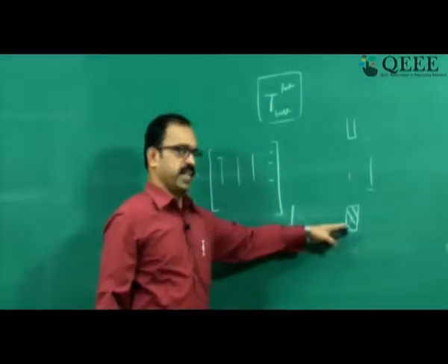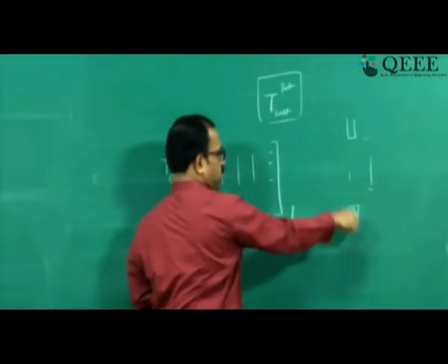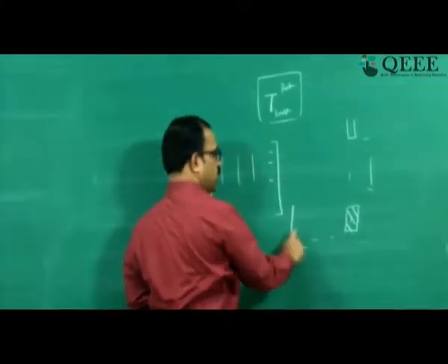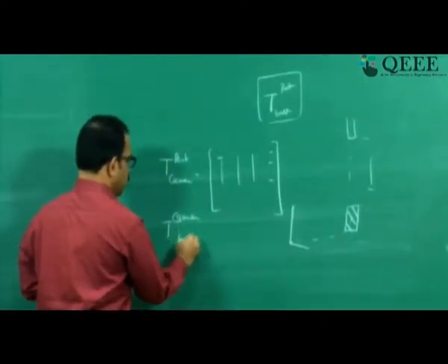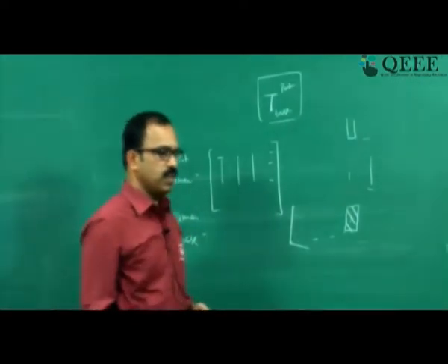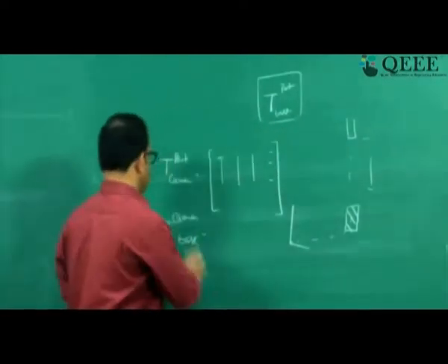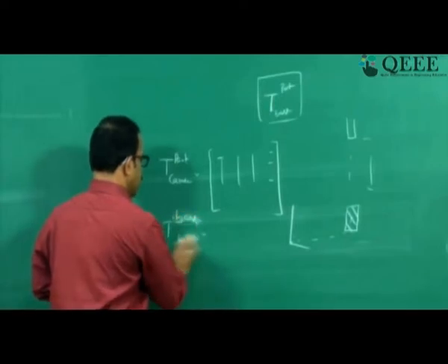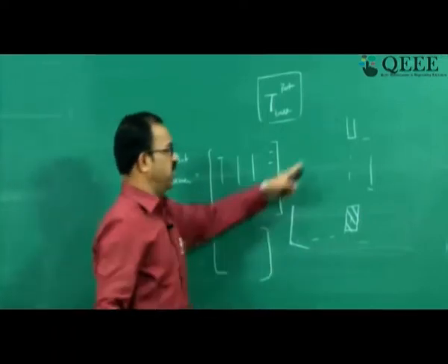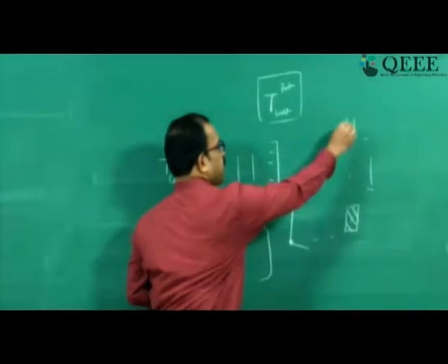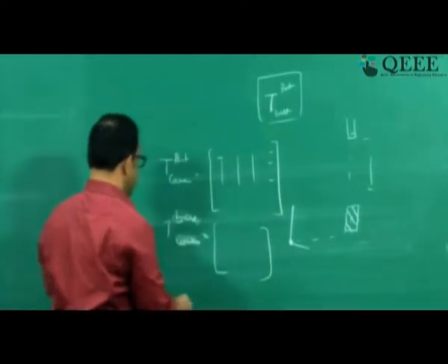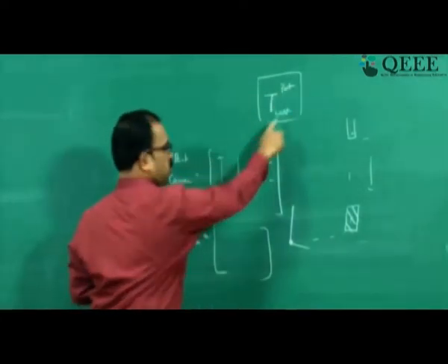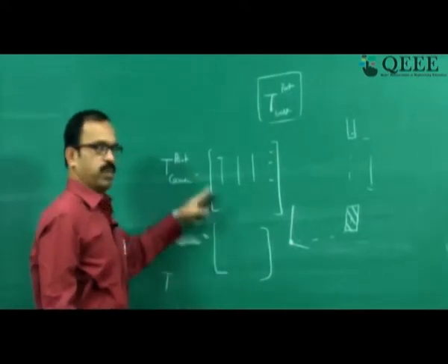Unfortunately the robot won't be able to get it directly, so it has to use this information and find out the position of the camera with respect to the robot base. So another transformation, camera with respect to base, or base to camera, any one of these, should be known. The transformation from robot base to camera is known because the camera is fixed, and therefore you will be able to find the position of the part with respect to the robot base using these two transformations.